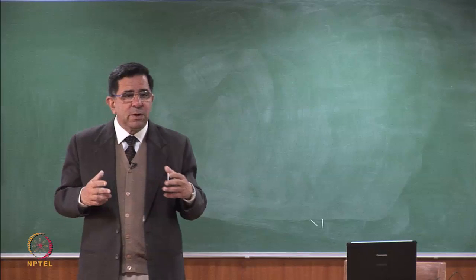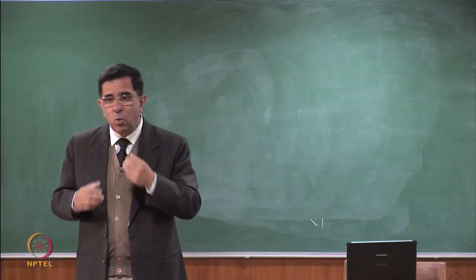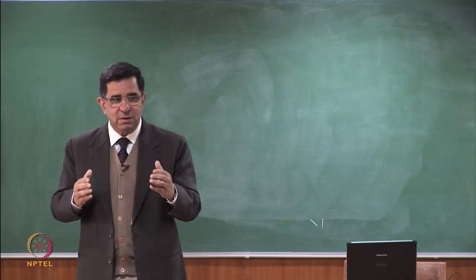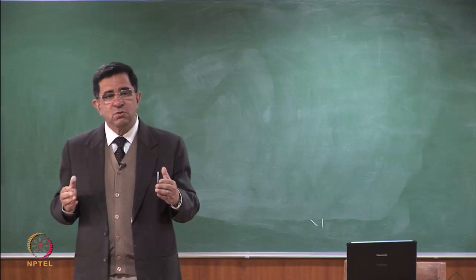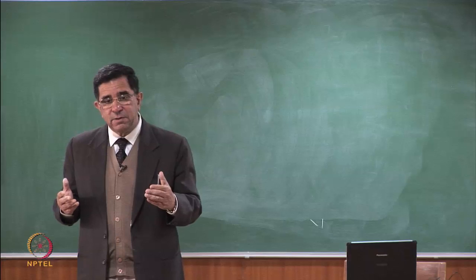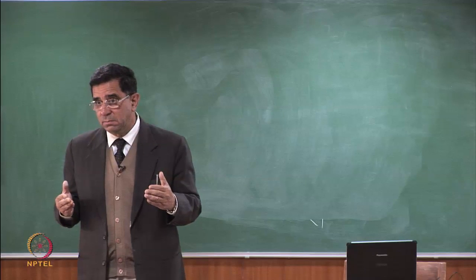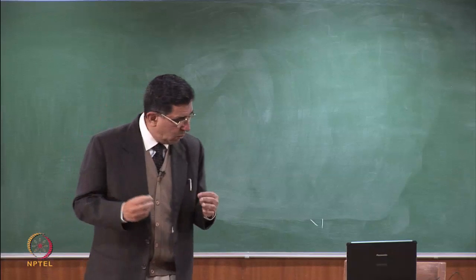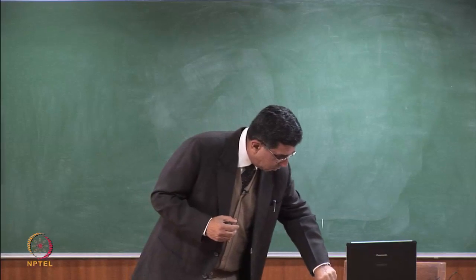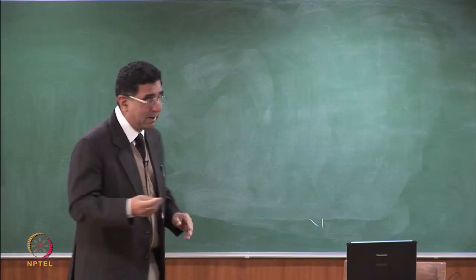So if a slope is coming out to be unstable, what is it that we can do to make it stable? So we are using a very gentle slope of 3:1. Last time I showed you that even with a gentle slope of 3:1, you can have a little bit of problem. So what all can we do? How do I make a slope stable? Simplest is I can make the slope flatter, right?